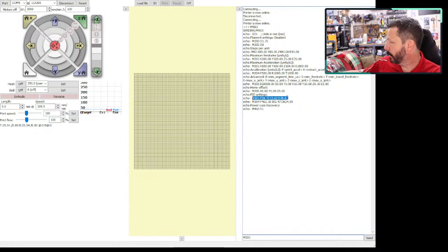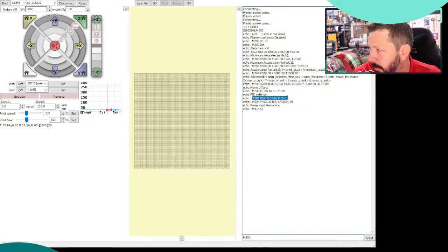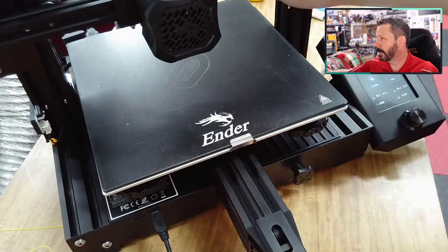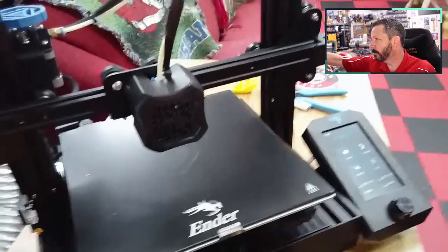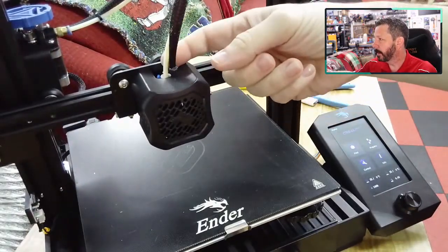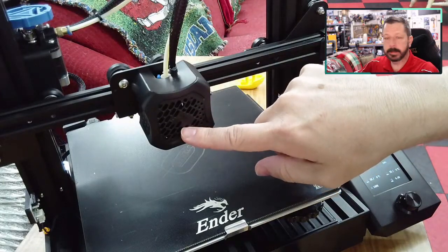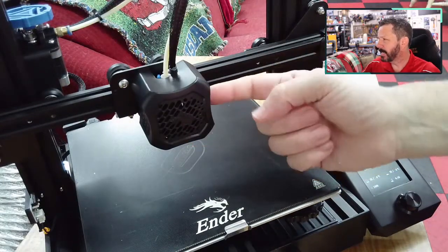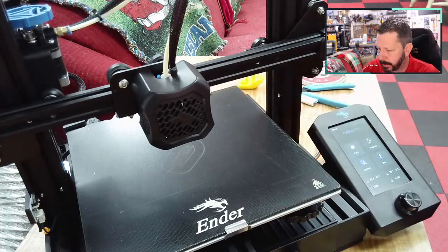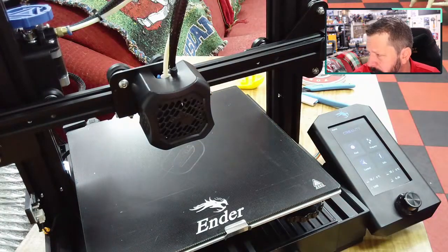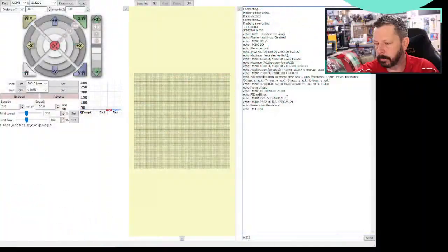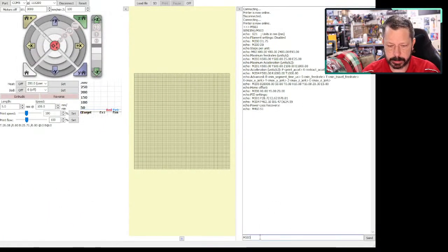So I'm going to load it. I've got the printer loaded with my PLA. Well, it's off the screen, but I've got it loaded with my PLA filament all the way down to the nozzle where it normally would be. PLA normally has this fan turned on, so I want to turn that fan on. I'm actually going to do that in the Pronterface. To turn on a layer cooling fan, I need another M command. M106 is the layer cooling fan.